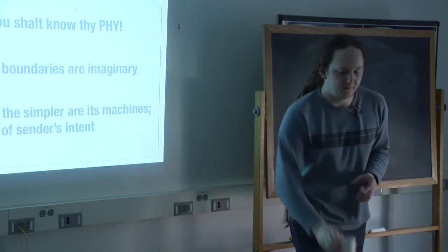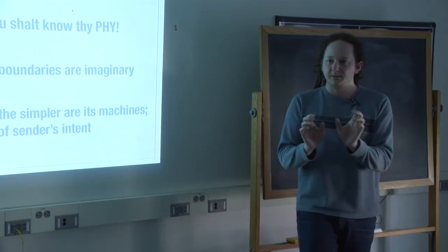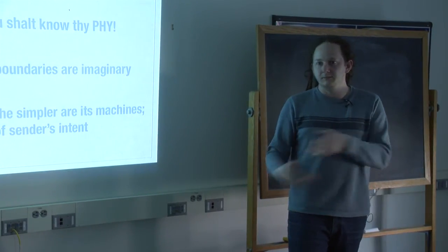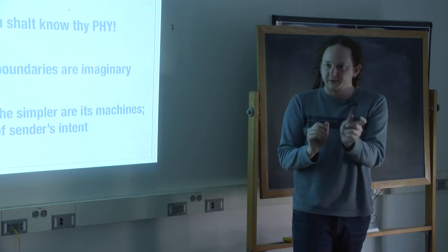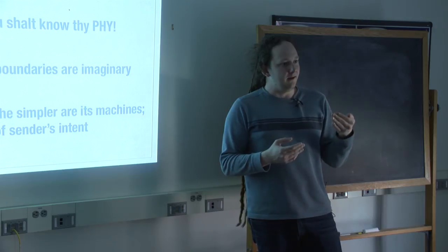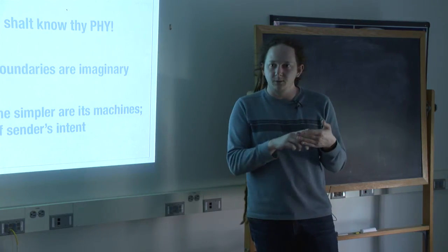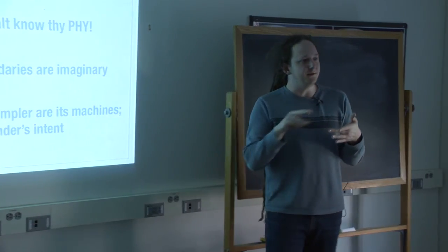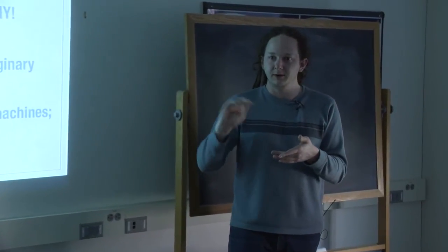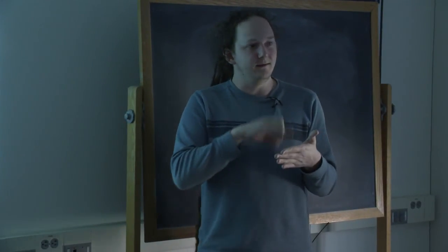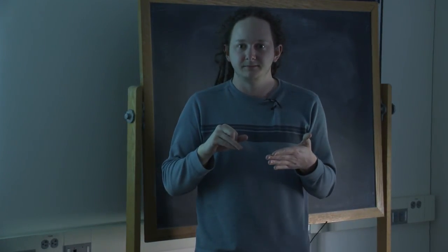The problem is that an Ethernet card, way back when, had physically separate chips for the PHY and the MAC. So the PHY takes the incoming symbols, decodes them, and puts those out on one wire. It has another wire that is a status indicator to mark that the symbols are good and meaningful. And then it has another wire that it pulses at the beginning and the end of the packet.